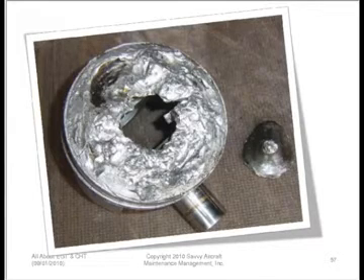He sent me the data on this. He said he was going to make a warranty claim because the engine only had about 75 hours on it since new. I told him not to waste his time because TCM never gives warranty consideration for detonation or pre-ignition damage. He made the warranty claim anyway. They turned him down, just like I told him they would. But this is a highly destructive thing.